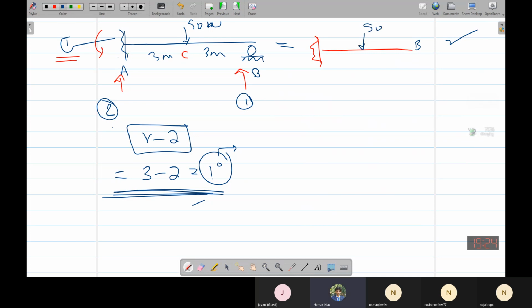This is a primary structure. It has the applied load, all the applied loading, but it is stable as well as determinate. Thus, now we are going to add the redundant structures. As the degree of indeterminacy is 1, only one redundant structure will be there, and it will simply consist of the same primary structure, but a unit load applied where we have removed the support.